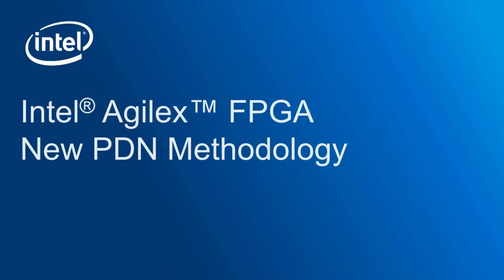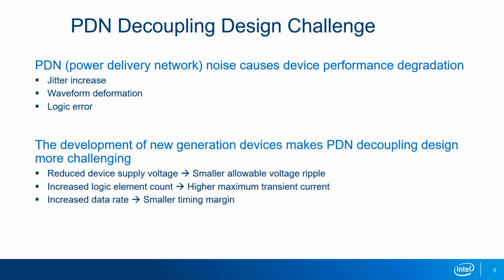Now let's take a look at the new power delivery network methodology in Agilex. The device under operation creates noise on all the power rails. This noise causes fluctuation in the supply voltage that can affect the device performance. Some typical performance degradations due to noise include increase in jitter, waveform deformation, and also logic errors. A good power delivery network design is essential for proper device operation.